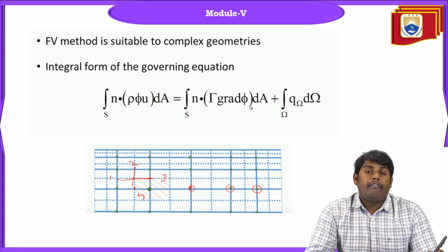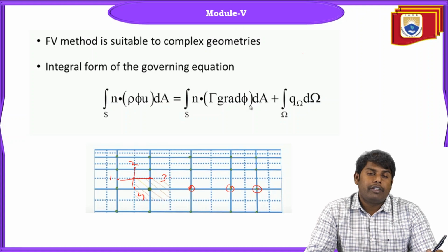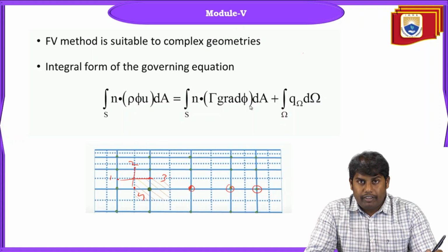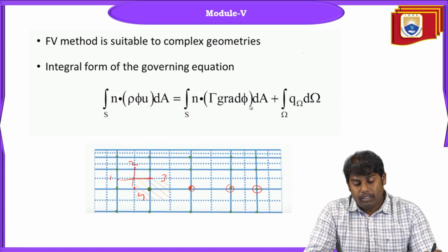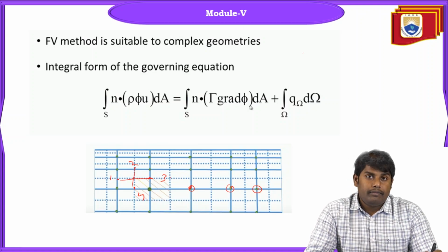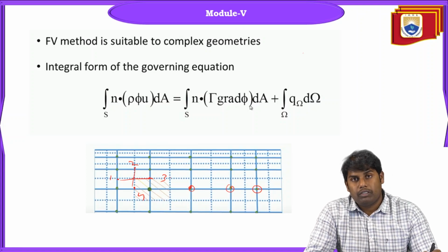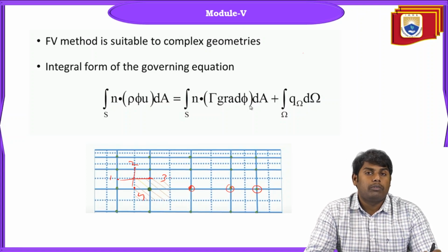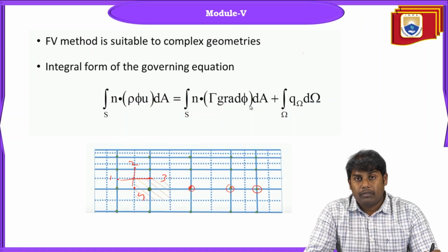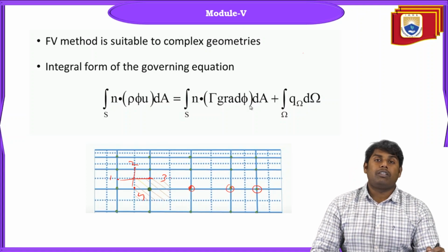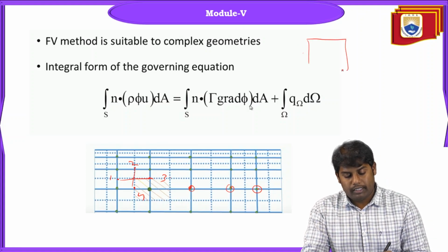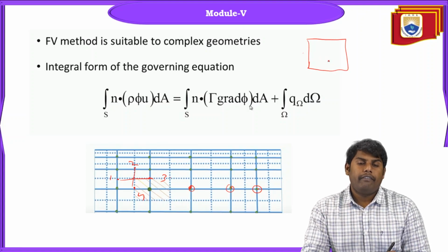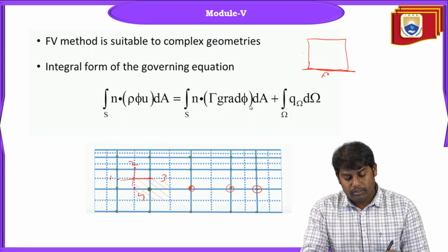When you compare the finite volume method and the finite difference method, we have seen that the finite difference method is applicable for structured meshes and for simple problems, not complex problems. For curved entities, applying the finite difference method is somewhat hectic. Simple geometry, in the sense, is, let's say, a square where you have a flat plate.